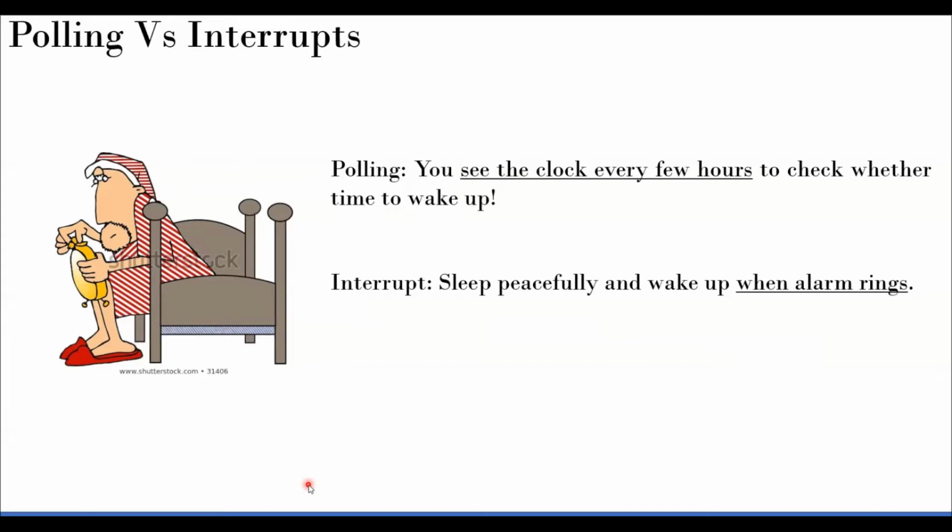Let me put some context into the picture. Last lecture, we discussed GPIOs, right? And we discussed how a GPIO can act as an input to a photodiode. So think about polling. In the case of polling, that GPIO register has to be read at a certain interval of time to see whether it is updated with the value in the photodiode.